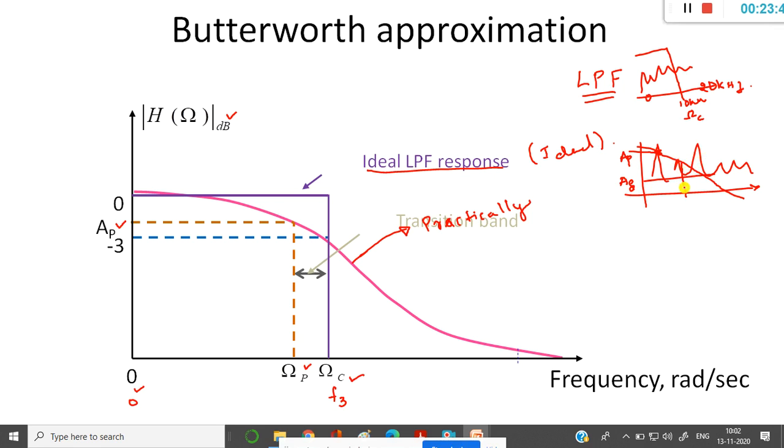And here also, some frequencies are passed and some cannot be passed completely, because it is not equal to the ideal curve. There is a difference of this many frequencies. I'm losing these frequency components here. When I design the practical filter, that is what we call the transition band. If you observe carefully, this is what we call the transition band.